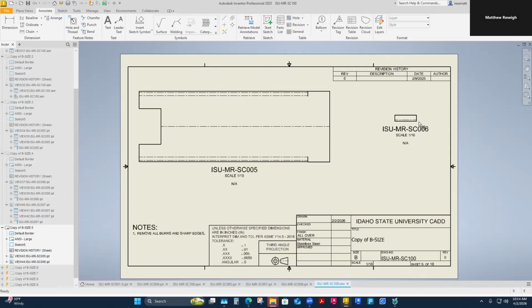And then I would have 3 parts on here. Eventually, I'm going to probably come name this the 12 gauge cut file sheet. I'm trying to think of them as being the same scale, just so if I have an old piece of equipment, the scale doesn't jack up the size of the part. That's what usually happens on old equipment. The first part that was placed on the sheet, it applies that scale to all parts.